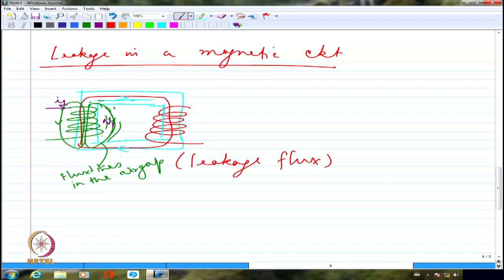Only then is it going to make better sense in terms of voltage production and so on. In this particular case, whatever does not link with the other member, we call that the leakage flux. The same thing holds good in the case of the secondary winding as well. I am probably going to have a flux like this and it can just link itself like this.